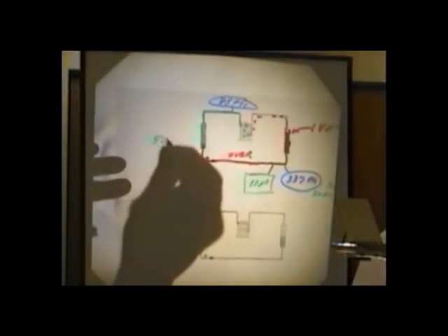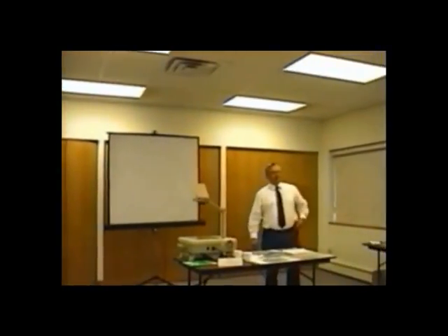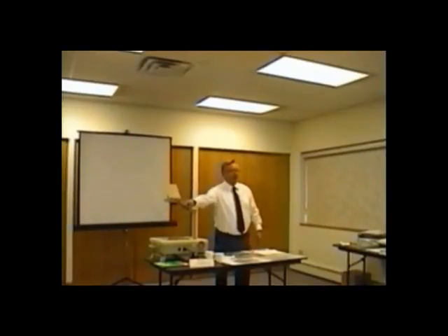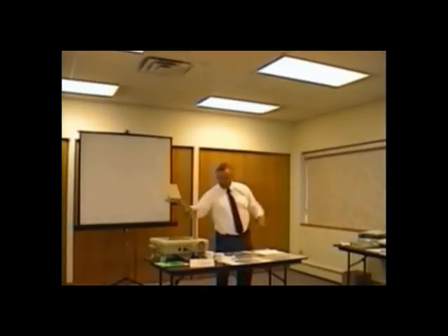Well, holy cow, I have a 50-degree evaporator now. Yeah, my pressure went up. 85 psi, gentlemen. My pressure went up. I have a 50-degree evaporator. And the technician says, the old-timers told me that if it isn't cold enough, grab the suction line and just keep adding more gas until it gets beer can cold. And I keep adding gas and they get colder. It's getting warmer. That's what happens.